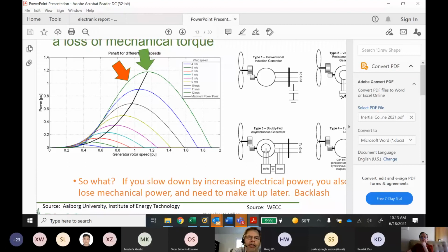There's a complicated relationship between the slip and the direction of power through this. So you have to be very mindful both of the frequency, the volts per hertz, and the ampacity of the bridge. There's nothing that says you can't build a machine that could tolerate even deeper speed excursions, but there's no good motivation to do so.